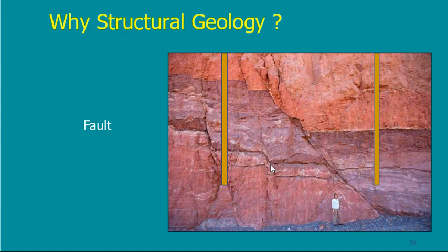If I do a site investigation and I find something not normal in the boreholes, I should add more boreholes, use geophysical methods, do everything so that I can get a clear definition of what is happening below in the ground. Is it a fault or not?